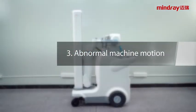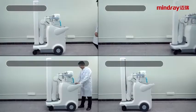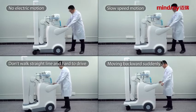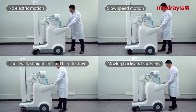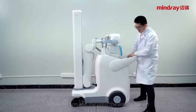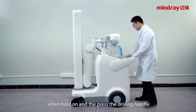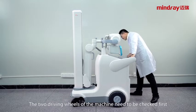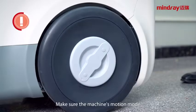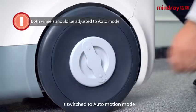Abnormal machine motion. No electric motion. Slow speed motion. Doesn't walk in a straight line and hard to drive. Moving backwards suddenly. There's no electric movement of the machine when you hold and press the driving handle. The two driving wheels of the machine need to be checked first. Make sure the machine's motion mode is switched to auto motion mode.